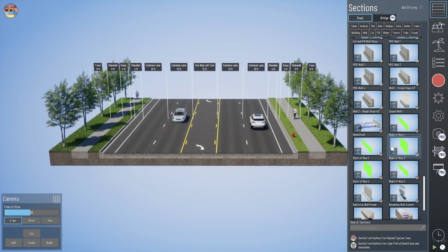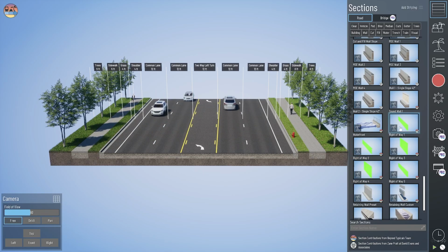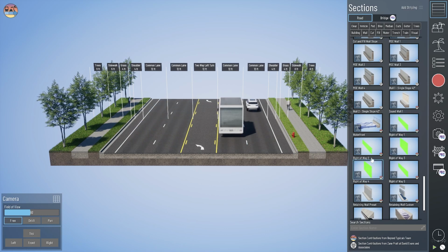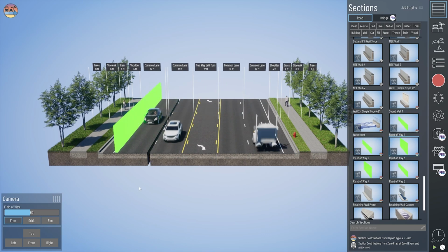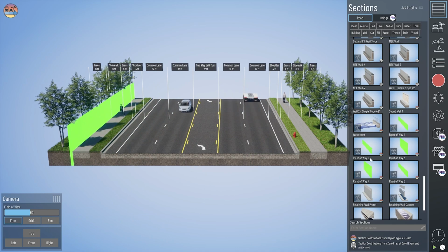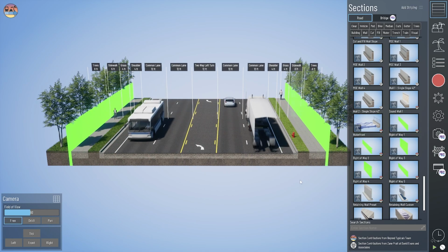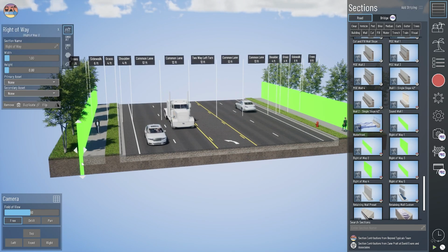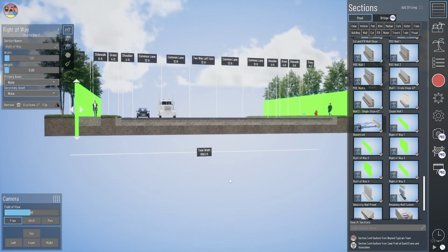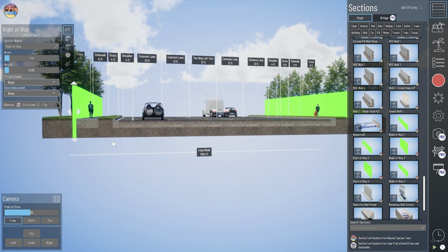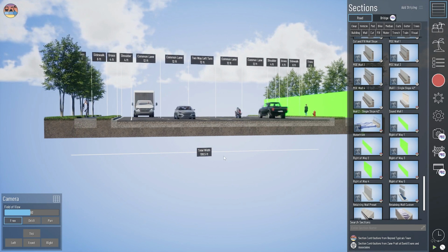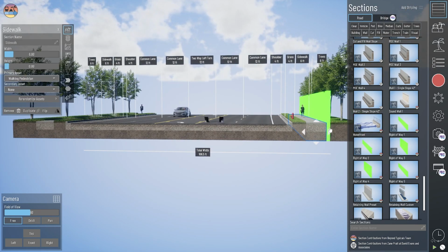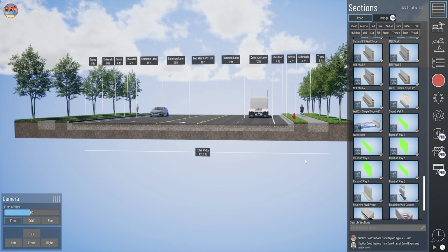Continuing from our previous video, in our road sections, we have these right-of-way visualization sections. Those are here highlighted in bright green. I'll show you an example of what these can look like. These are elements you can bring into your model to show right-of-way lines. Keep in mind, these do add a width by default to your section. So you'll see that when we select these, they're a foot wide. And when we delete them, the total width at the bottom will change.